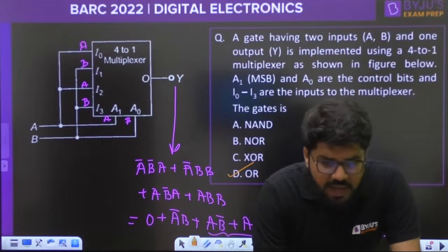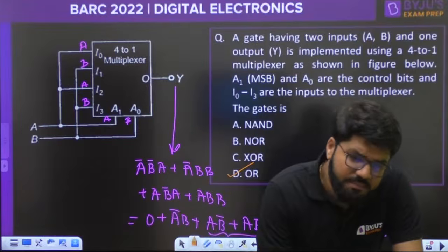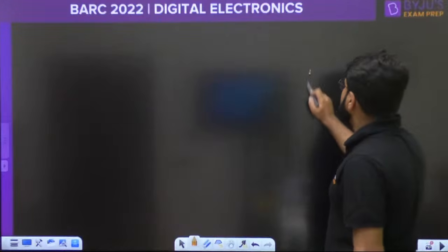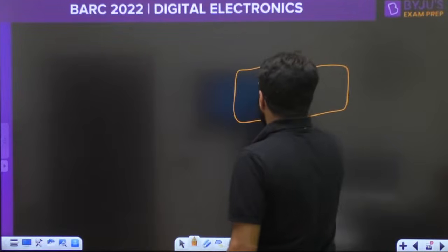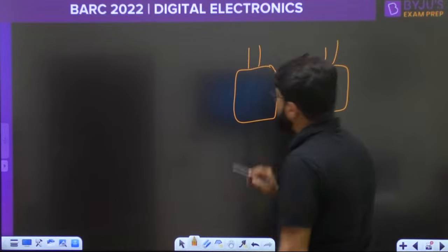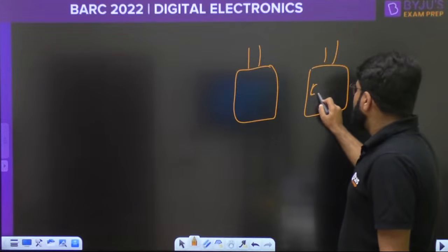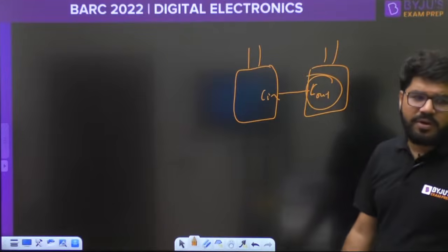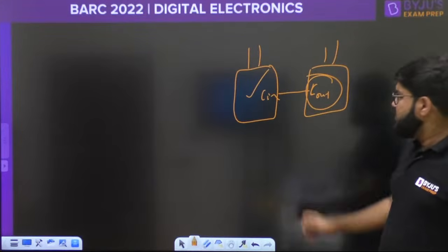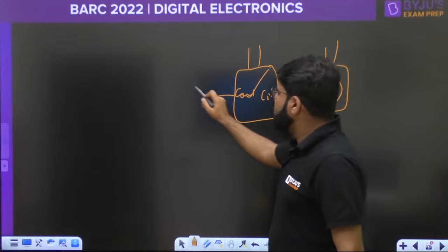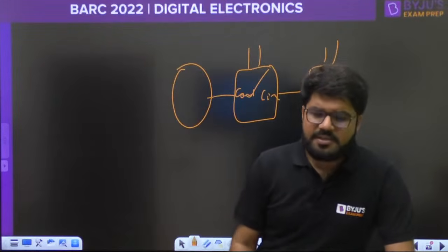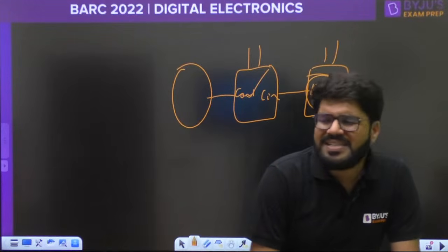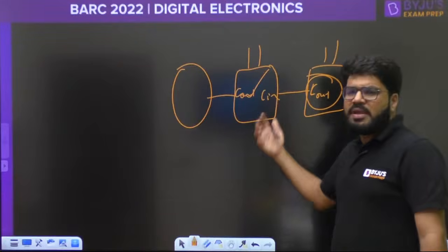Surajit, in a parallel adder all the bits will be applied simultaneously, but look at the ripple carry adder. Suppose I take a 2-stage case only, you apply both the inputs, but this has a carry output, which goes to the carry input. So unless this gets the carry output ready, how can the second adder start? Similarly, when this gets the carry output, then only the third adder will start. Isn't it, Surajit? That is what makes the ripple adder slow. It's a simple design, but it's a little slow because every adder has to wait for the previous carry.